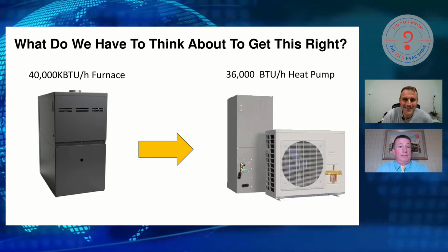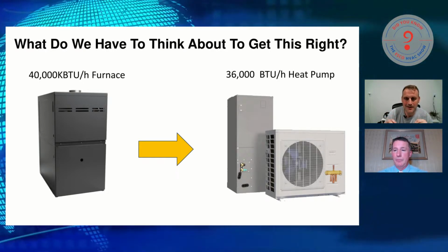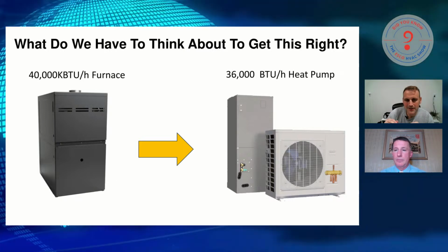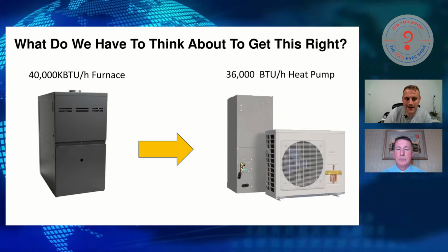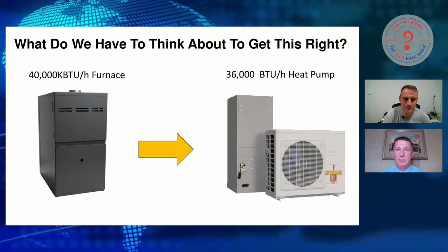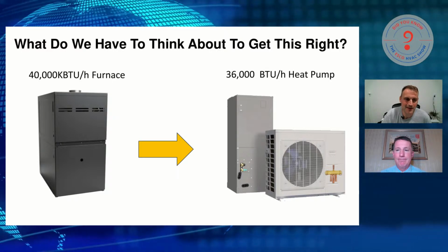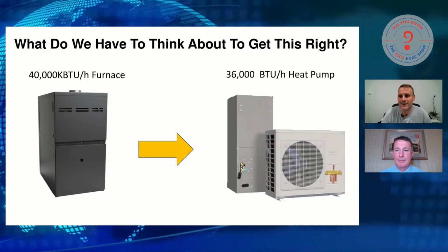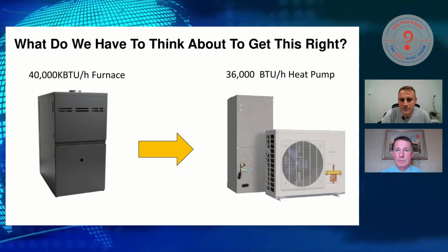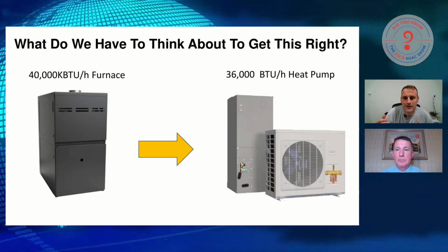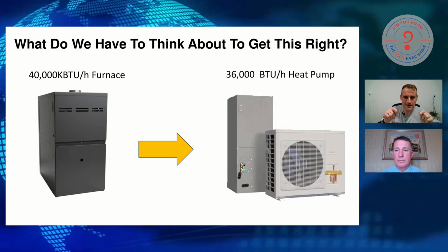Do I have the ductwork? That's a radical difference of capacity. What I'm trying to say is the furnaces don't necessarily have to move nearly the amount of air to get the same heat capacity to the space as a heat pump does. A heat pump's going to have to move like 3 times more air for the same capacity, roughly, right? So knowing what your ductwork is capable of is crucial when you're going to make a utility swap on what the equipment's going to run on. And this is the world we're facing right here.